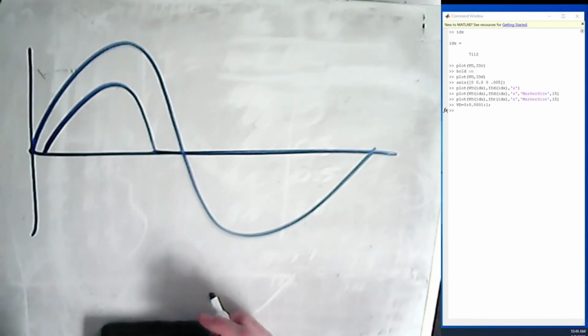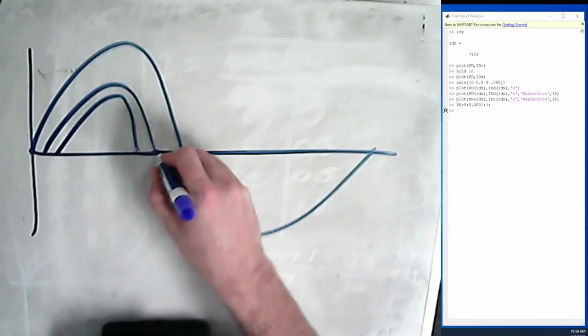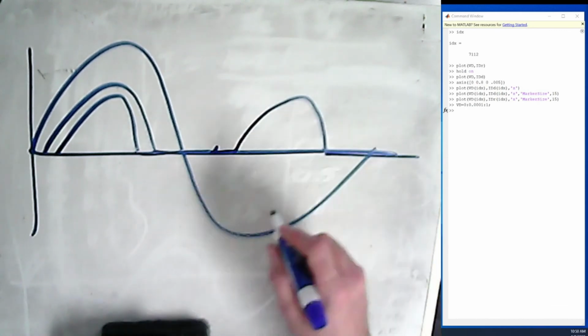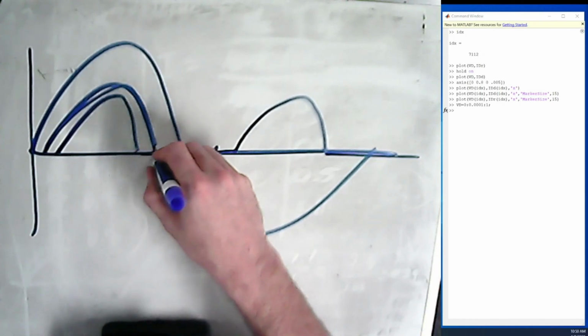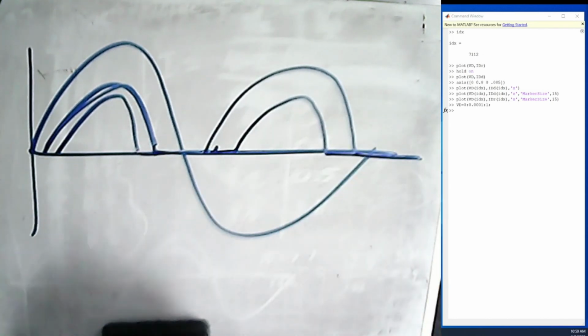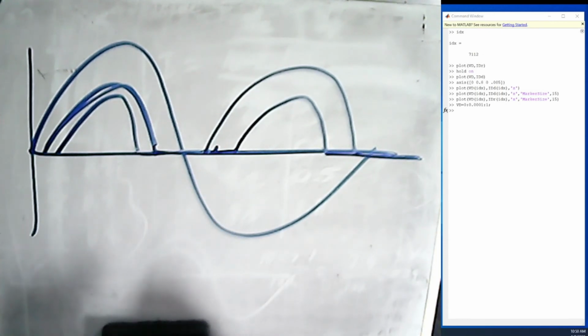When you go to the bridge rectifier, each time you pass current, it's going to go through two diodes, and so you're actually going to have a 1.4 volt drop, and so you're less efficient. The bridge rectifier is good. The bridge rectifier, so that was the bridge rectifier. The full wave rectifier is going to give us that 0.7 volts drop, but there's a downside to that, which is one's the transformer, and one is that we're going to have more reverse bias voltage on those diodes. Can they handle it? That's one of the questions we have to ask in the future.